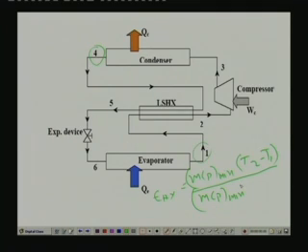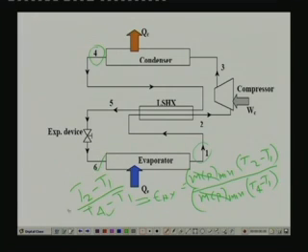So, delta T maximum is T4 minus T1. The m Cp get cancelled. Finally, effectiveness of heat exchanger is simply given by T2 minus T1 divided by T4 minus T1. From the data we know T1 and we also know T4, and effectiveness is given as 0.65. So, we can find out the exit temperature T2.